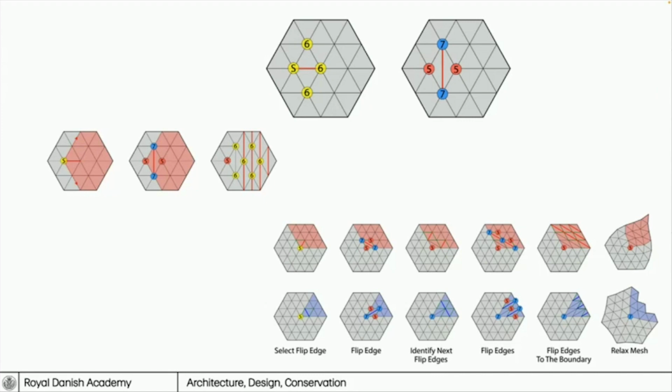And there are some very simple mesh operators. We're using one that is called flip edge. You can see what we're doing up there. S is the singularity that we want, and we want to turn that into a 5, not a 6. So the valence really refers to the number of edges that are coming into the node. As we flip that edge, you see that we generate the 5 that we want on the left, but the collateral damage is that we've generated a 7 above it, a 7 below it, and a 5 next to it.